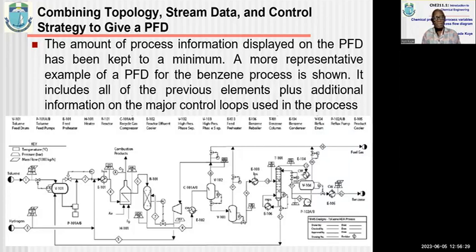So here you can now see our PFD diagram in which all the information is put in place. Yes, you can do this because this is a fairly small process unit, so you can put everything on the same page. But if it's a bigger one, just like we said, you need to put them separately. You need to put the stream summary in a separate table, and the equipment summary in a separate table.